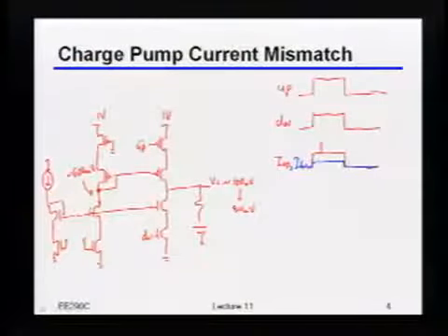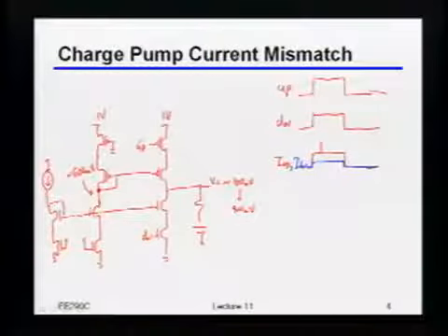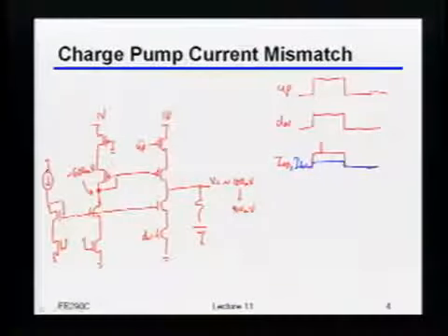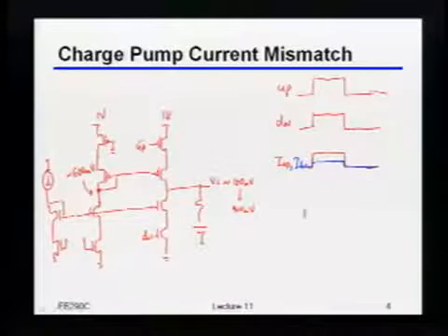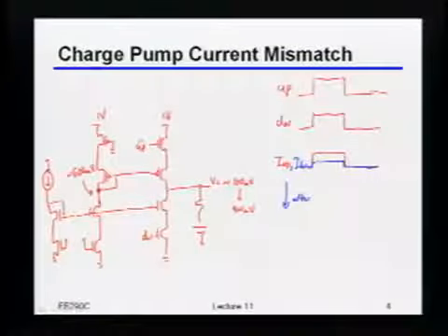Which one has to get wider? Yeah, that's right. I down has to get wider, right? Because since it has less current, you have to integrate it for a longer period of time to actually get the output to be correct. Okay, so let's actually draw that situation. Now I'll draw the currents after some time, after you converge, or let's say after locking.